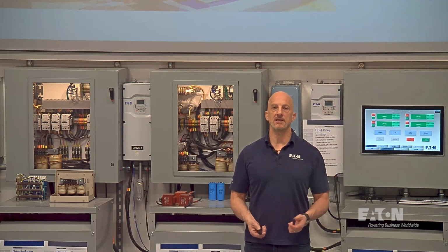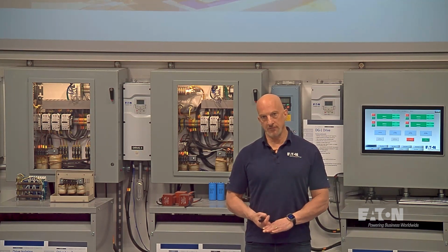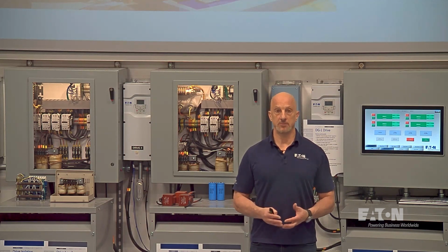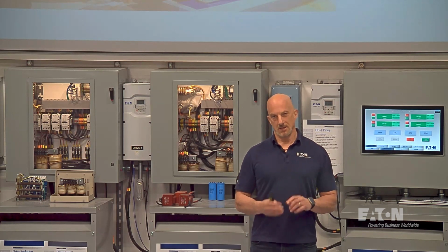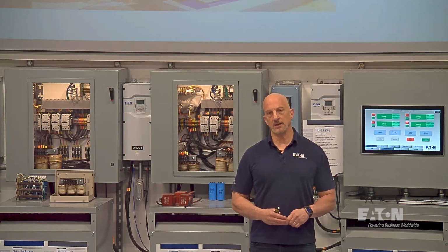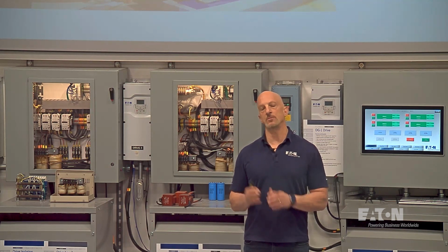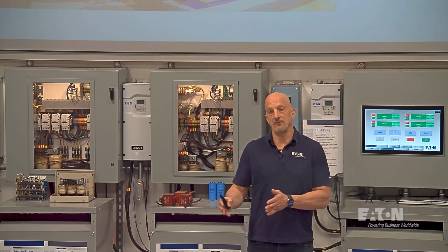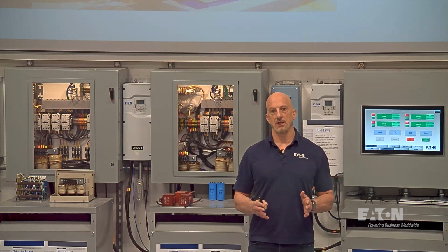But at the end of the day, how do harmonics affect your power bill? They don't directly affect it because we're billed on power factor displacement, which is 60 hertz only. How they can affect it a little bit directly, but more indirectly, is through the losses. And those numbers are in the 1 to 4% range. So if you put a harmonic filter on, for example, and you eliminate all your harmonics, you can save 1 to 4%. You can't save 20% of your bill just with getting rid of the harmonics.